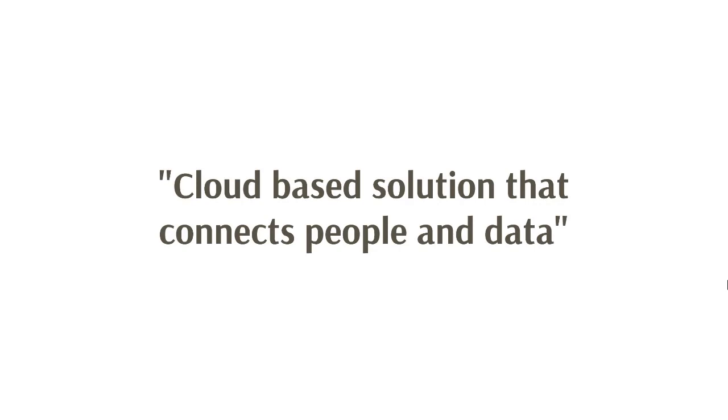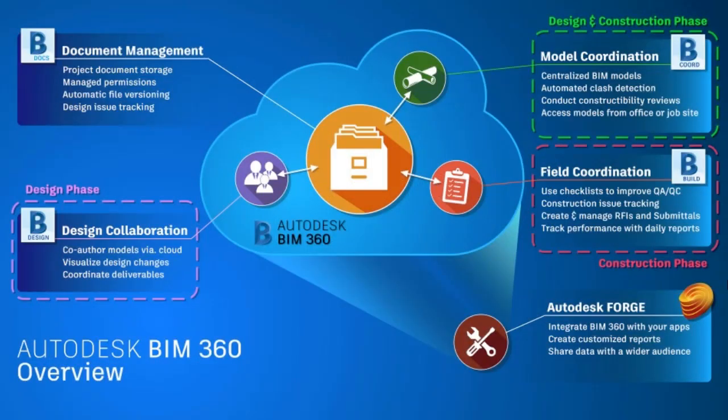To facilitate this, Autodesk has created a cloud-based solution that's going to help connect people and data, and that solution is the BIM 360 platform. In the BIM 360 platform, the core of the platform itself is BIM 360 Docs, and what the Docs are is that's where our files are stored. That's where we're going to create users and manage permissions.